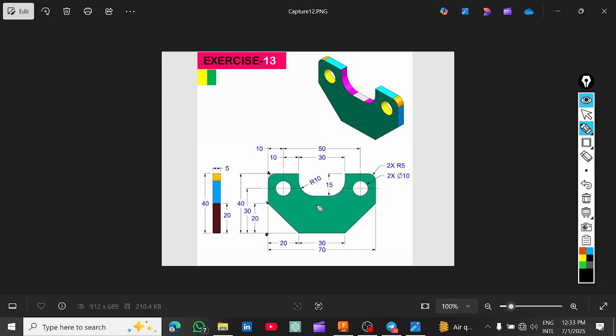So we are going to add another point here. When we are done doing this, you find out that it's very easy to use points and dimensions to create simple geometry such as this. Okay, so we are going to add this other point here, 40 millimeter from here or 20 millimeter from this other end.